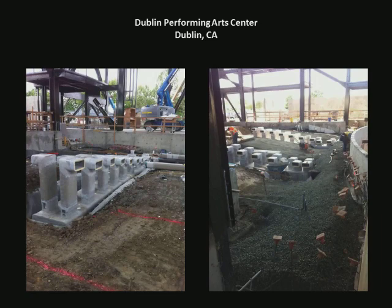Another great application for displacement ventilation. Auditoriums have very high ceilings. We don't have to cool the entire room. The air is coming in at a slower rate. This means people are less likely to get a draft from a vent blowing straight at their feet. And the air can come in a little bit warmer because we have less of a cooling load.